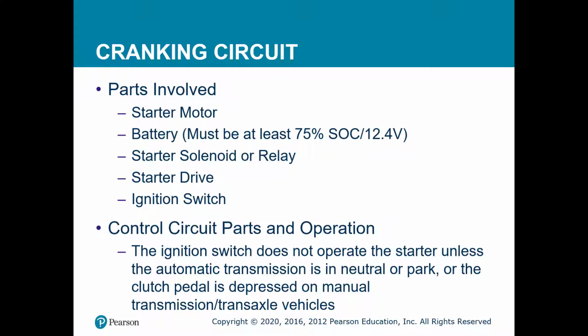In my experience, I've received some vehicles where they thought the starter was bad. Well, when I stepped on the clutch, it fired up. They just weren't stepping on the clutch enough. The other thing, too, is I will try to start a vehicle in both park and neutral to verify that it's not the neutral park safety switch.